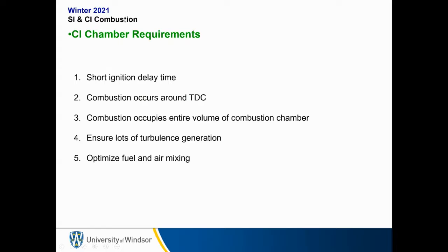What are some requirements for compression ignition chambers? Well, we want a short ignition delay time. We don't want to have a long delay between injecting the fuel and ignition. We want combustion to occur around top dead center, so our pressure spike is giving us positive work. We want the combustion to occupy the entire volume of the combustion chamber. So unlike spark ignition, where we only want combustion to happen at the propagating flame front, in compression ignition, we want combustion occurring in the entire chamber. We want every single droplet burning as fast as possible. We want to ensure we have lots of turbulence generation. Again, that's so we make sure we have tons of mixing. And then 5 really follows from 4. In that 5, we want to optimize the fuel and air mixing.